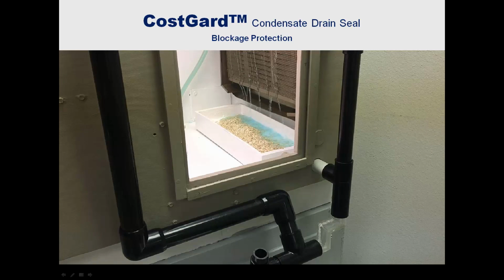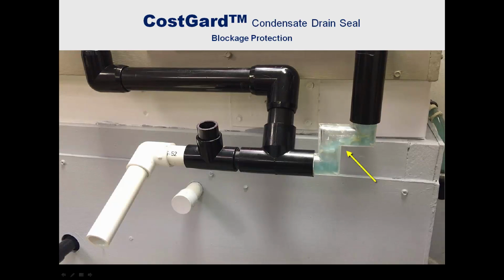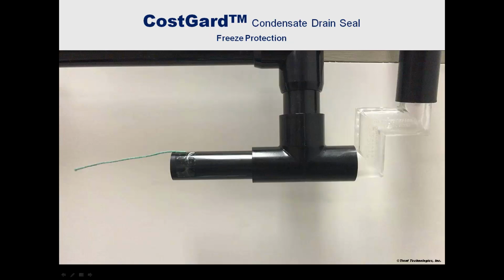Perhaps the most recognized problem with a condensate trap is that it catches debris and becomes blocked. This happens frequently, often after only a few months of operation. The CostGard condensate drain seal inherently guards against such blockage. This special CostGard device, equipped with clear plastic elbows, shows why. Here, soggy oatmeal is used to simulate the slime that often clogs drain lines and traps. Note the churning action produced by the air entering the device and the rapid passage of the debris.